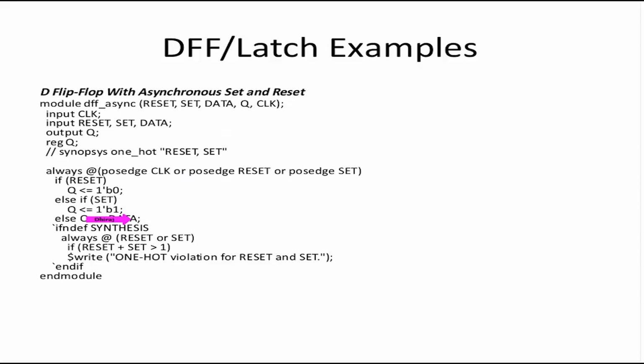Okay, let me explain this. With the ifndef synthesis, this part of the code, these lines, the synthesis tool will discard. It will not use it, because if ifndef synthesis is written, that means the synthesis keyword is not defined.